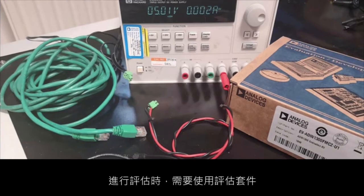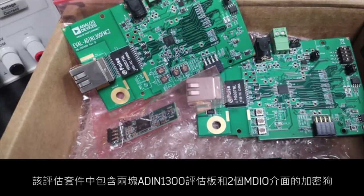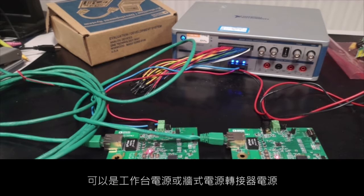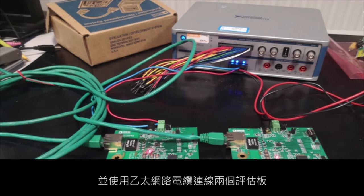For your evaluation, you will need the evaluation kit, an Ethernet cable, a 5-volt power supply, and 2 USB mini cables. In the evaluation kit, there are 2 ADI 1300 evaluation boards and 2 MDIO interface dongles. So to get started, you need to connect both boards to a 5-volt power supply. That could be a benchtop supply or a wall adapter. You'll need to connect the MDIO interface dongles to the boards and connect the Ethernet cable between the 2 boards.